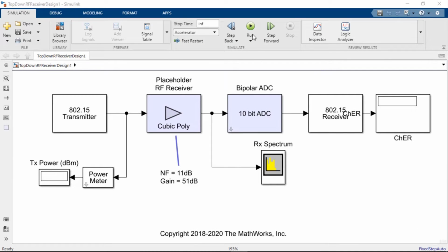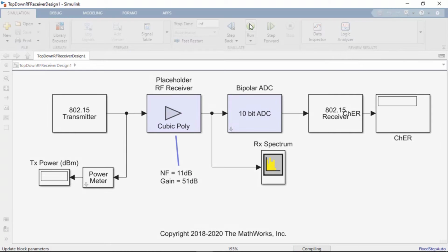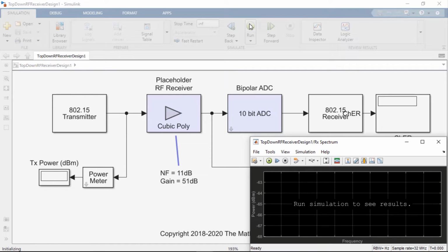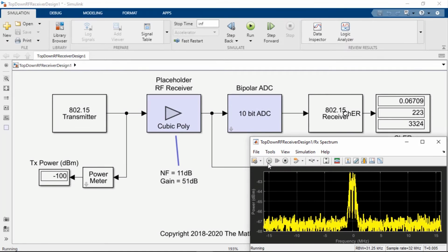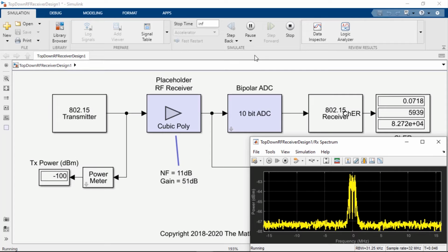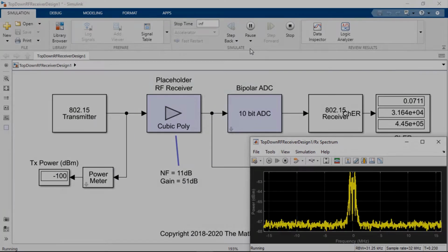This is a simple model of a communication system. The specs are directly taken from the Zigbee standard. In this test bench, we test the receiver at the minimum power sensitivity level, with the transmitted signal with power level set to -100 dBm and a bandwidth of 2 MHz.